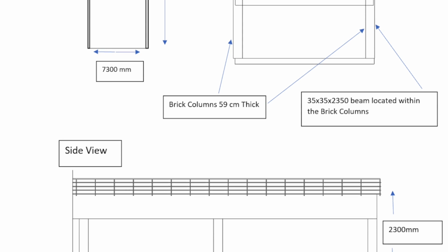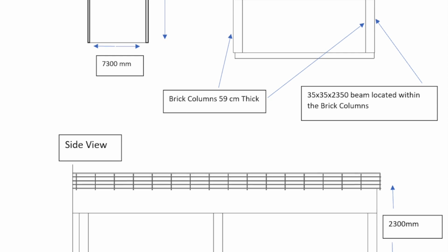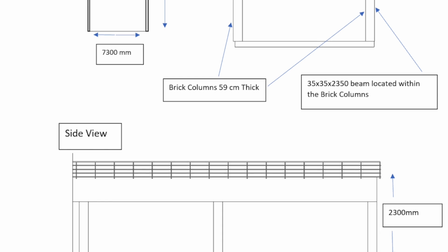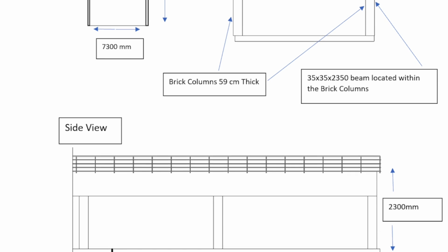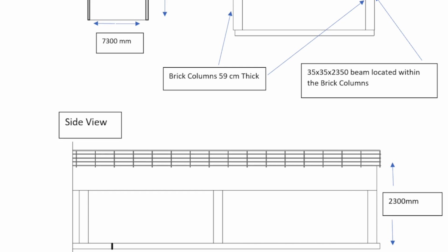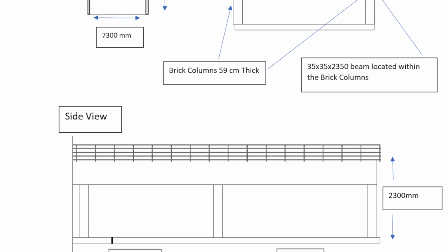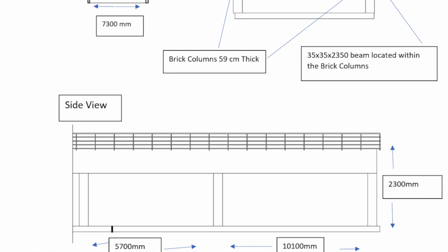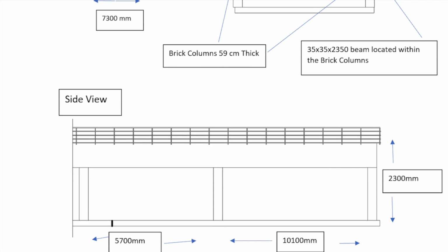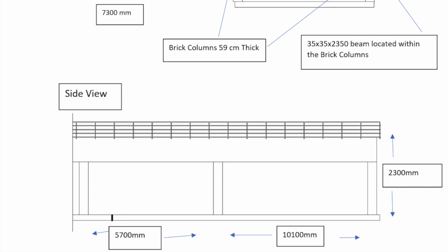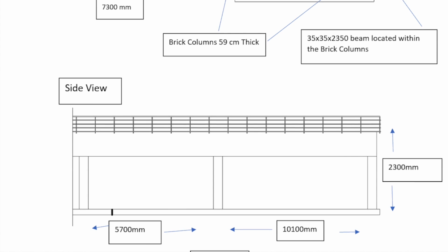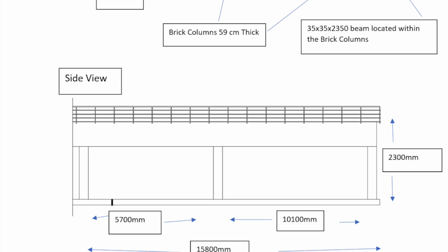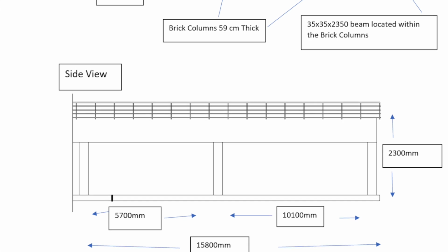The 3 lateral beams connecting the columns to hold the slab up are 760 centimeters in length, 35 centimeters in width, and 74 centimeters in height. The 3 longitudinal beams are 570 centimeters in length, 35 centimeters in width, and 74 centimeters in height. Surrounding the outside of the bridge are 5 safety railings. These railings are 730 centimeters in length, 10 centimeters in width, and 124 centimeters in height.